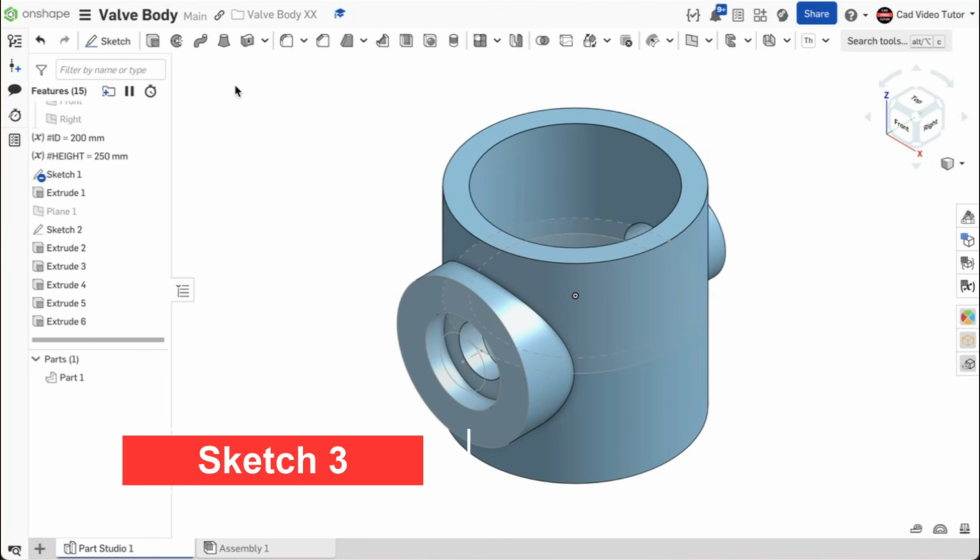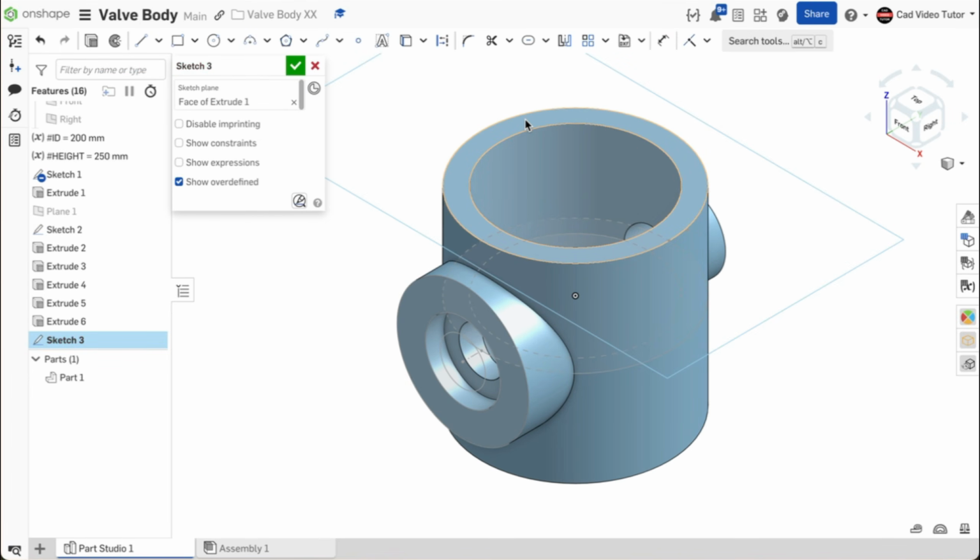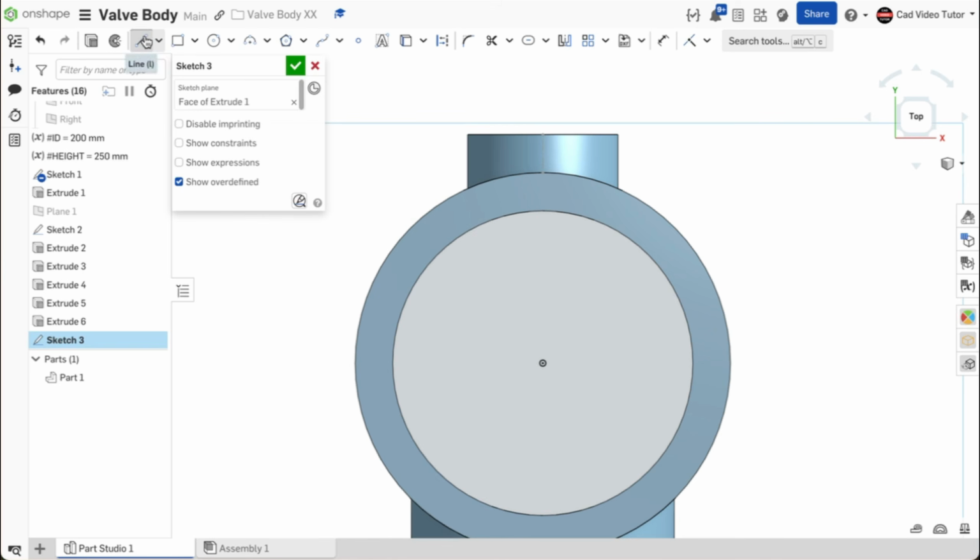Start a new sketch and click on the top face of the cylinder for the sketch plane. Use N on the keyboard to view normal. Click on Line and Construction. Hover at the origin and move up to the inner edge of the cylinder. When you see the vertical and coincident icons, click to start and stretch a vertical line. Double-click to end. Enter 60 millimeters for the length.